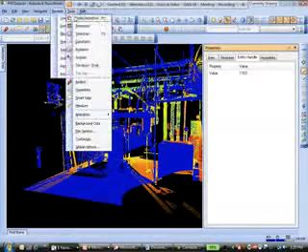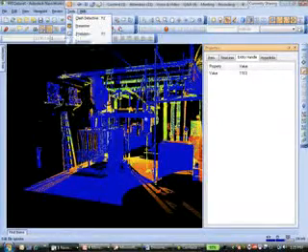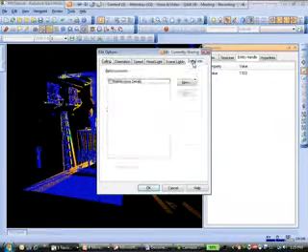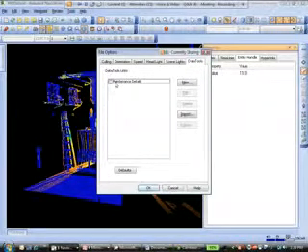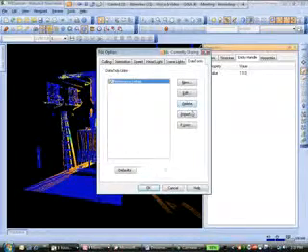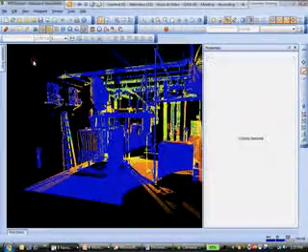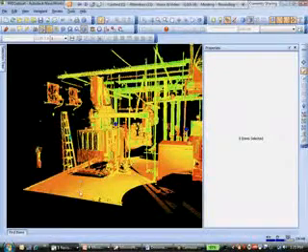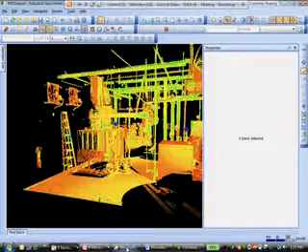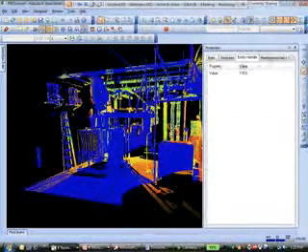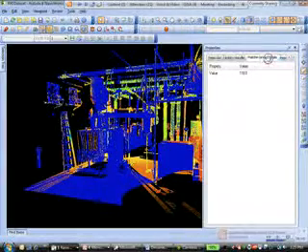So in doing so, if I go to File Options and create, selecting the Data Tools, I can now embed maintenance information into this existing as-built. So I'm going to select OK. And now what I've done is I've created a SQL script, this is part of this data tool, that says link out to that Access database. And when I select this, now it gives me a tab up here for maintenance details.